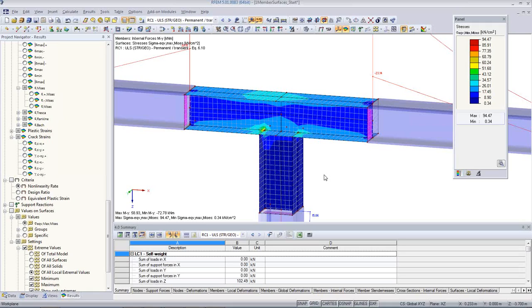The way the software works, it compares the existing stress with the limit stress, the yield stress of the material, and then has an algorithm that reduces the stiffness and the elasticity modulus of those elements. Because we can only reduce the stiffness of the entire finite element, we cannot evaluate, or we should not evaluate, the result separately in each node of the finite element.